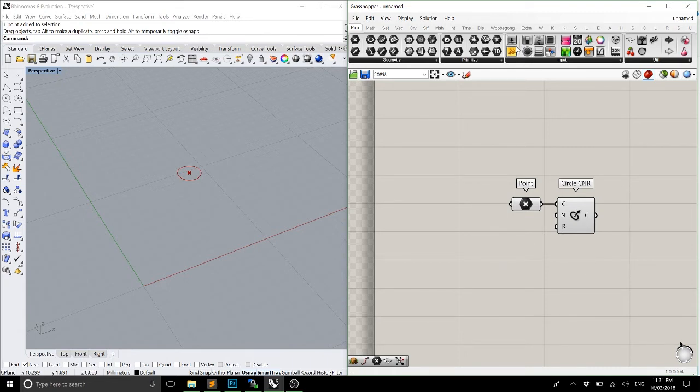So instead of getting a slider the way that I did before, there's a few shortcuts, and that's by double clicking. And you can grab other components if you know their name off the top of your head. But if you type any number, so for example, if I typed 5, and I keep forgetting this, and hit enter, then it'll generate a slider for you with that number, and it'll set the minimum to 0 and the maximum number to the nearest factor of 10.